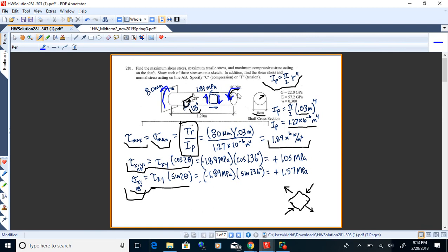You just take the directions of the torsions, both the applied and reactive torsions, acting on the face of the shaft, look at their directions, up or down, and just move those over as shears, up or down. That's what you do. And then realize that the other shears meet in the corners. Okay, so there you go. There's a shear element. Remember, there's no normal stress in the x and y directions. So that's the shear element that you'd get.